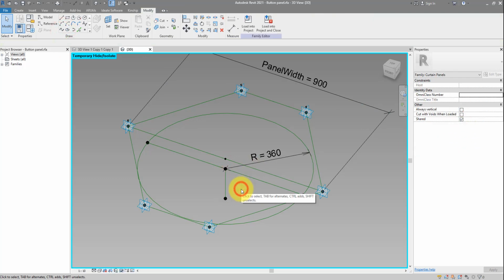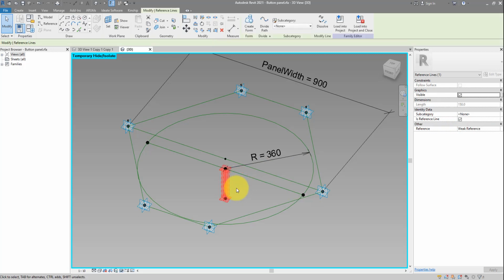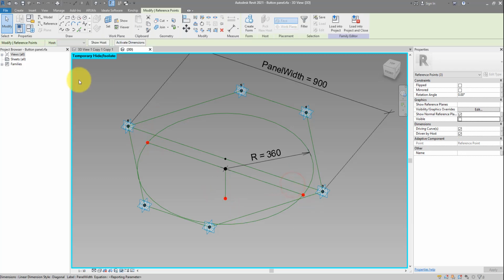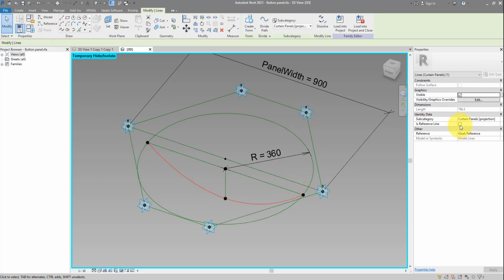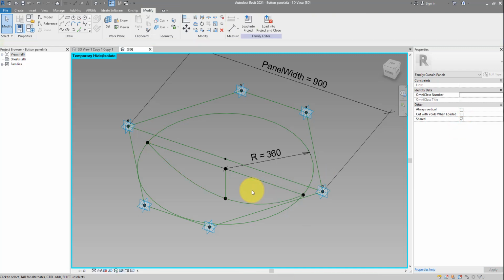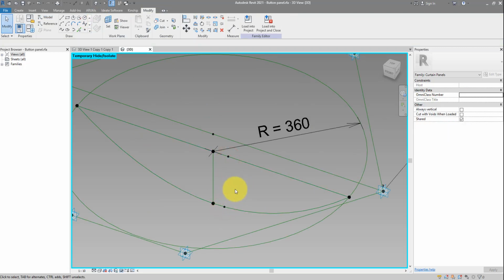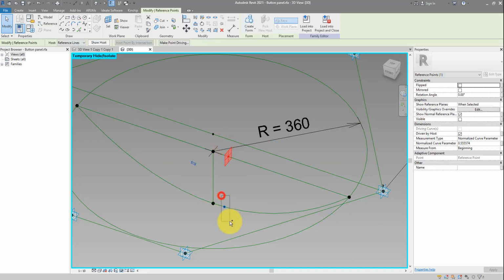Now, if you are familiar with making Revolve Forms in Revit, this is similar. This will be the axis of our Revolve, and now we need to draw a profile for the Revolve to use. To make that happen, I need to connect this point and this other point there. That will create a reference arc. I can now go ahead and place 2 more points on face, at this location, and this location. Let's now connect them using another reference line.